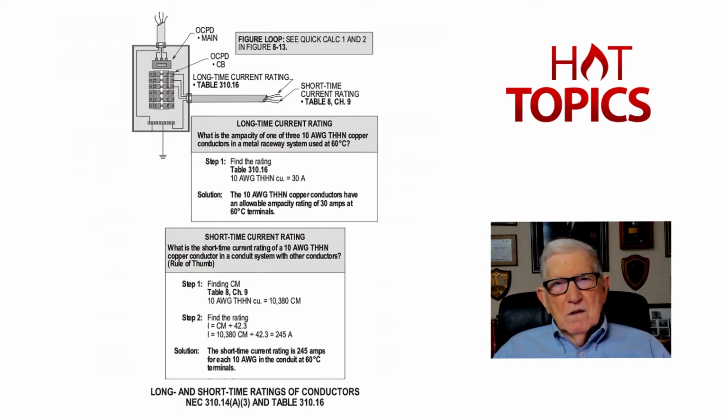So we know we find that in 110.14(C)(1)(a). If you're over 100 amp load, it's automatically 75 degrees C terminals. So your terminal ratings, naturally you look up the requirements in 110.14(C)(1)(a) or (b), based upon the 100 amp or less rule, or over 100 amp. So we would pick that up.